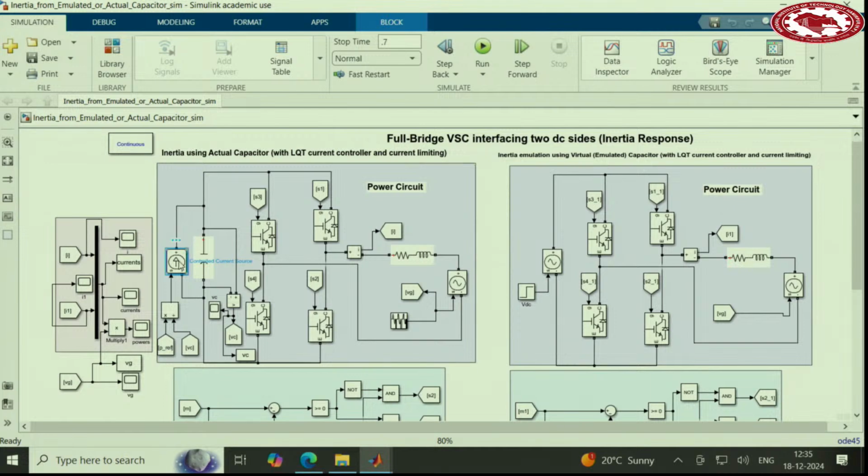So choose that current equal to the power divided by VC. So the amount of power, P reference or P set point, divided by VC, that is the current, and then you apply it to this controllable current source, and that means that this amount of power, P ref, will be coming from here. This is a scenario where you have 2 stages of converter.